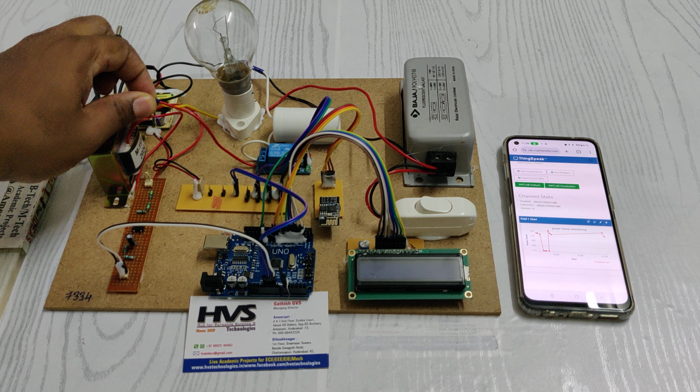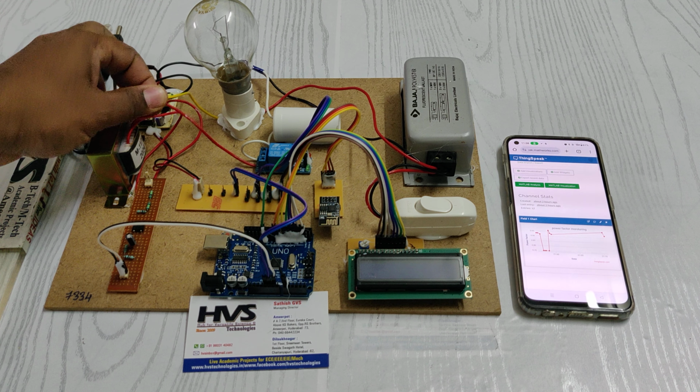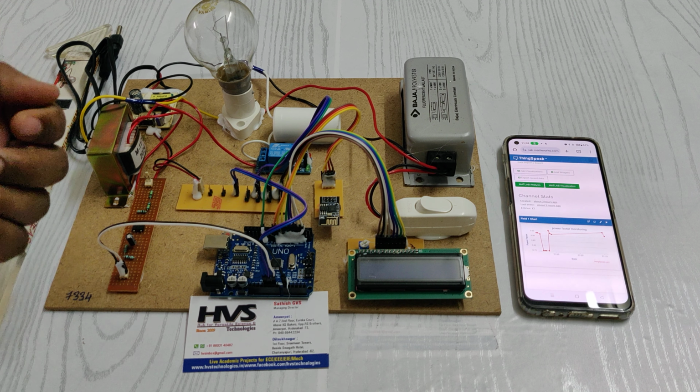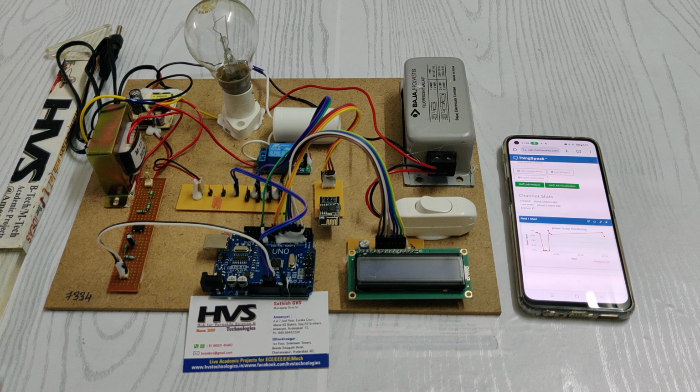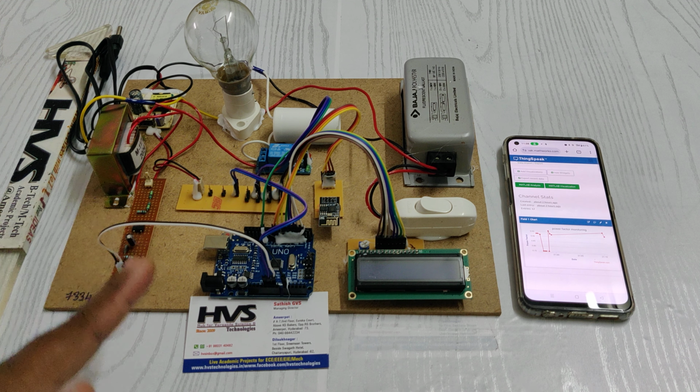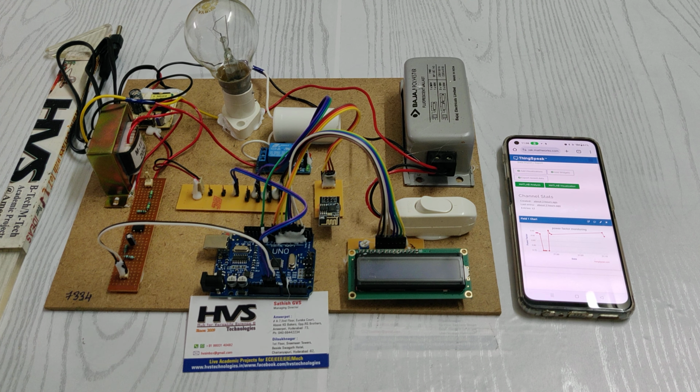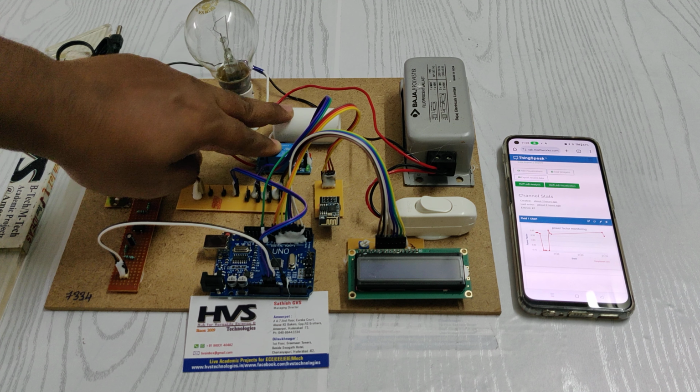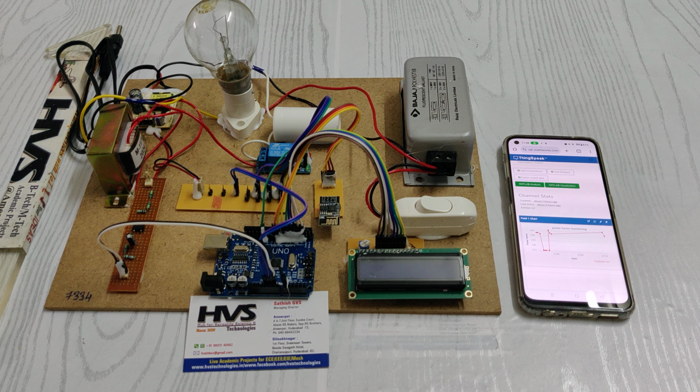Here you can see we have connected it in parallel with the help of this relay. In that manner, the current waveform will lead, and the phase difference between these two waveforms will come down from some value to near zero. Then again we maintain the power factor at unity. Whenever it is above 0.9, we consider it a normal power factor, which is nearly unity power factor. Whenever it is less than 0.9, the system will switch on this relay to connect this capacitor in parallel to the R plus L loads.